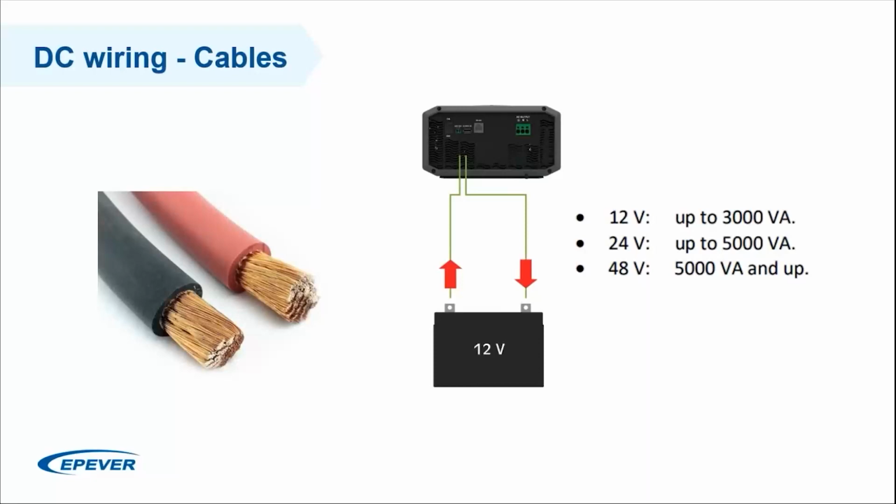Voltage drop is not desired in off-grid systems because it causes a lot of problems. Voltage drop happens when the current travels through the wires. If your wire is thin, it will have higher resistance, and then you will have higher voltage drops, the efficiency of your system will be lower, and it will cause other problems such as thermal problems or heating.